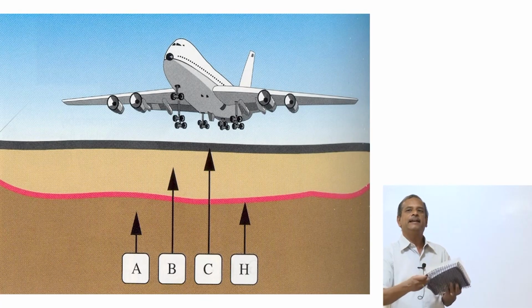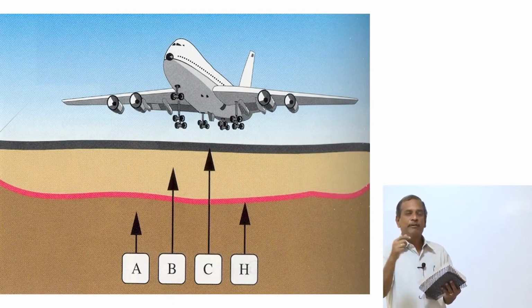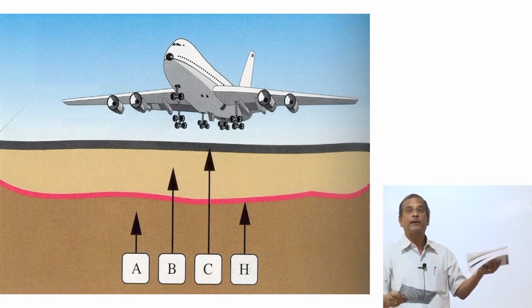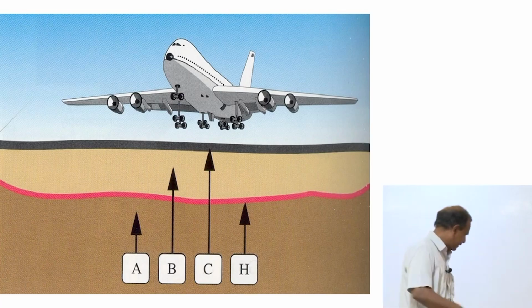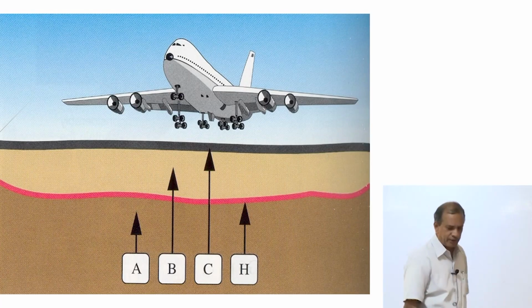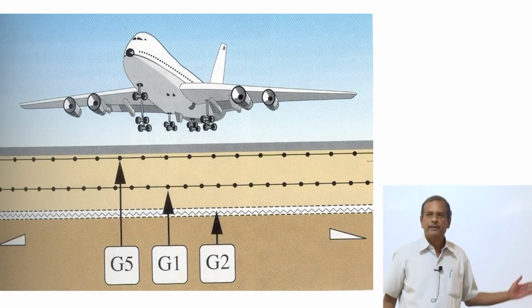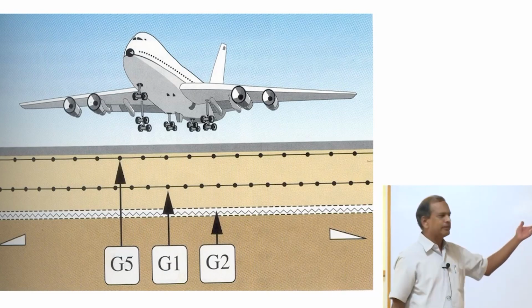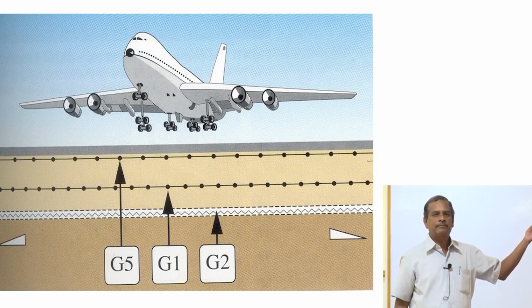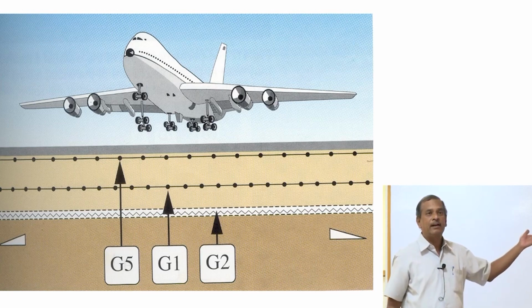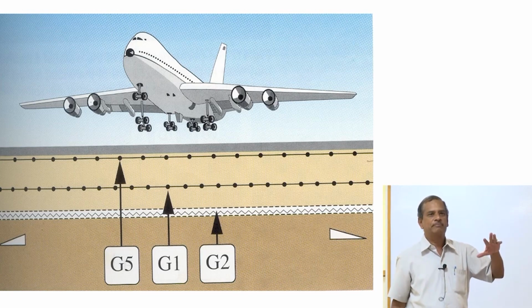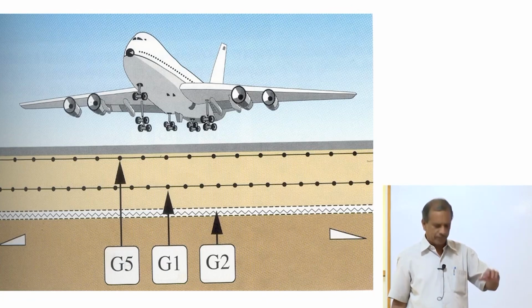So, this again has to be done only by a civil engineer. So, everything costs money. If you introduce a new material, that's an improved performance at what cost? So I can improve the strength of the subgrade soil by introducing geogrids here. So you can find the 2 layers of geogrids laid there. The runway or a taxiway can last longer without a deformation. No rutting, no cracking will occur.